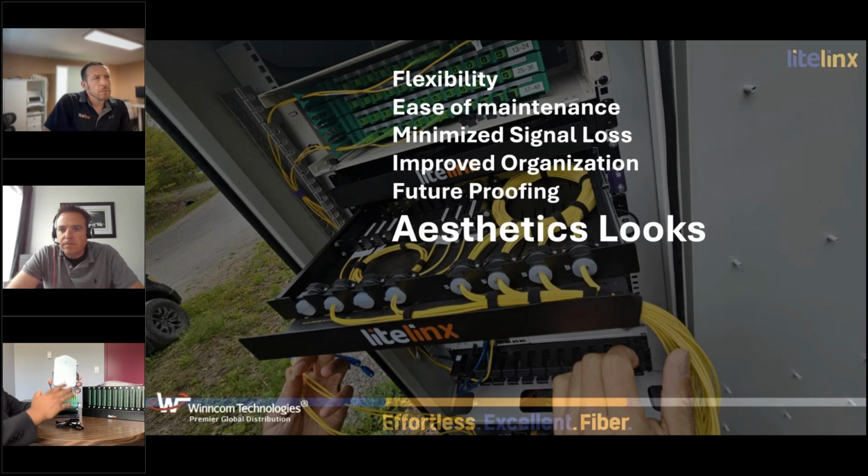Now when it comes to the splicing side, you can bring the fiber cable inside from the other side. It provides you a ribbon splice or single splice options right there. For the entire 12 fibers, you can do a single ribbon splice, and you are connected to your main passive network there. And as I said, depending on how many ports you want, you can remove or add these cassettes and keep it that way. In the front, there is complete cable management, with cable support trays available here.